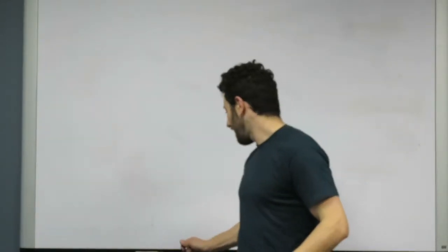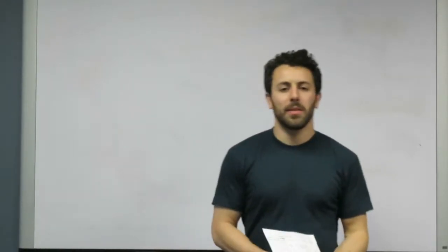The last section of torsional stress that we have to discuss is, I know, your favorite, and probably the most confusing of this class: whenever we have what I call a static indeterminacy. So again, just the same as axial that we went over 2 weeks ago, you have too many unknowns and not enough equations of equilibrium. And we know the typical equations of equilibrium being like summing x or y forces, or the moments in the x, y direction, and the moments on that member of analysis.